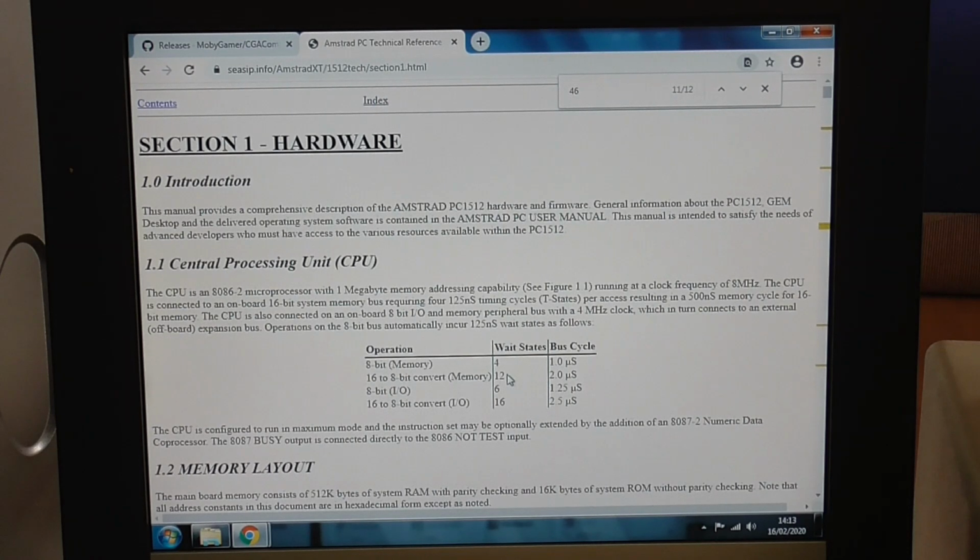And so that's how I figured out that I can actually detect when horizontal retrace occurs by finding the optimal pattern of memory writes and no-ops in between those writes. I can actually determine exactly when the horizontal retrace occurs. And so this was how I managed to figure out how to do raster bars on the Amstrad PC1512.